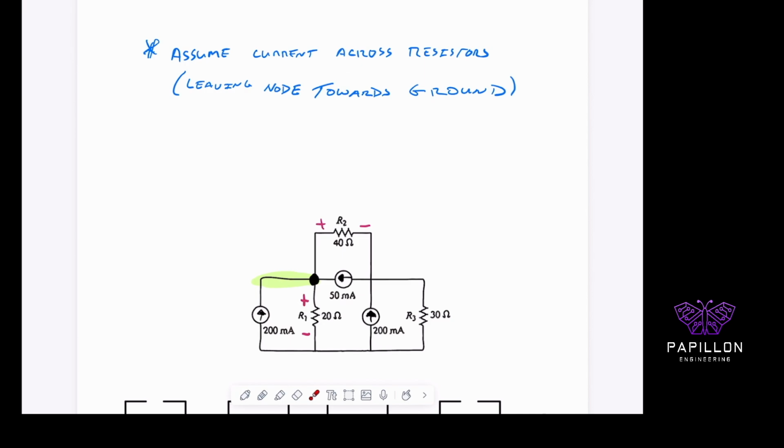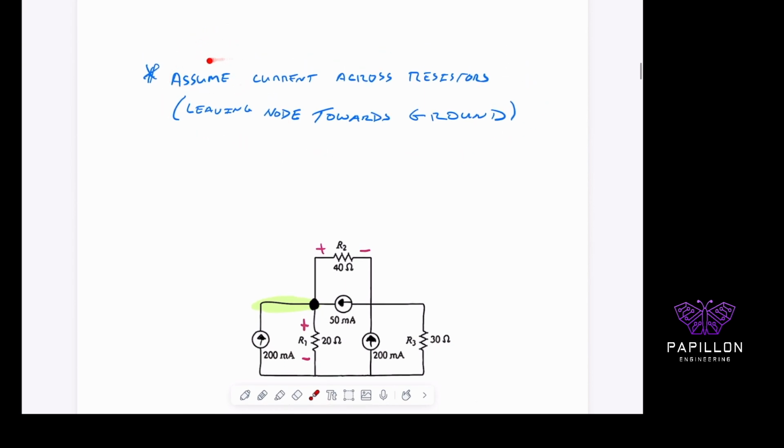Okay, so again, anytime I see a resistor in nodal, and I'm not given the direction of the current, I'm going to assume that the current across the resistor is leaving the node. Okay, it's really important. So leaving the node means that I'm expecting the current flow to go like this, with a resistor and a resistor always. The current sources, based on the arrows here, are telling me the direction of the current. So for example, here, this arrow is pointing upwards, which means the current's definitely going into the node. I know that with certainty because they're telling me that. Same over here. The current here is entering that node because the arrow is pointing into it, which is really important. Again, because of resistors, I am not given that information, so I'm going to assume, it's a tough word to swallow in engineering, that the current across those resistors is leaving that node, always. As long as you're consistent with that, you will always get the correct answer.